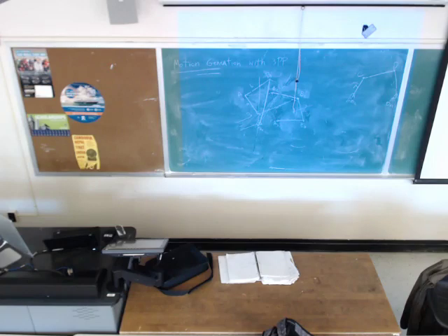When it's moving from right to left, the forward motion, it's going to remove material from the surface. Since it's doing some job, it should move slowly. But when it's going back to the starting position, it doesn't do anything, so on the backward or return motion, the speed can be faster.